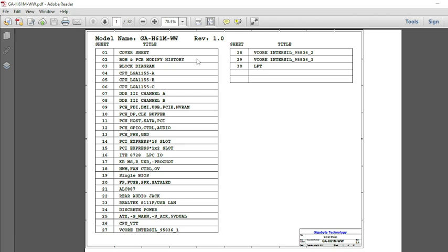Sometimes you will not get the GFX voltage. For that, you have to do the BIOS work with the help of a BIOS programmer. In each and every Gigabyte motherboard you will have a main BIOS and a backup BIOS. You can remove the main BIOS and shift the backup BIOS to the main BIOS place, by which you can turn on the display of your motherboard and repair it. This is the simple trick.